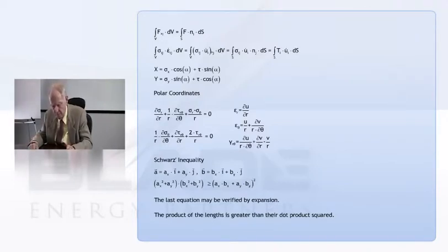So it works in several forms, but what you're doing is you're saying, and let me say this: if I was going to do this again, I would put a dot over the strain and the displacements to convert them to strain rate and velocity, because that's the way we use it most of the time, because that's the way in plasticity you normally think of things, as stresses and velocities.